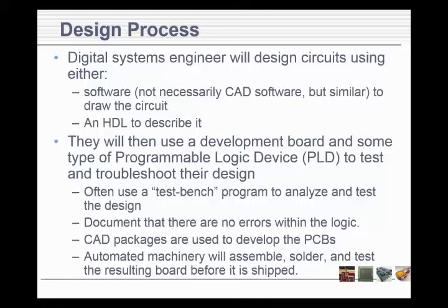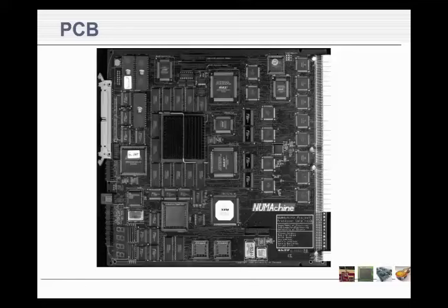Then they download it to the programmable logic devices that are there to test and troubleshoot and see if it is working. Often they use some kind of test bench program in there in the middle. That's what I was getting at. That lets you test it, lets you simulate it.